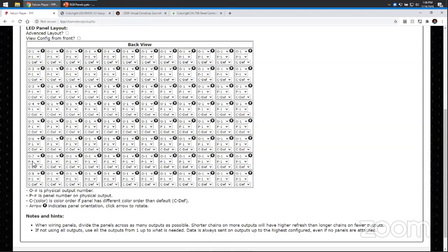So here would be your 8 output channels. But to be in that 256 by 256, you're going to be able to get 4 wide by 8 tall. And that's going to be the full refresh rate for one Colorlight card. So I divide this thing into 3 sections and put one here on this 4, and then start another one right here for this 4, and then a third Colorlight for this 4.